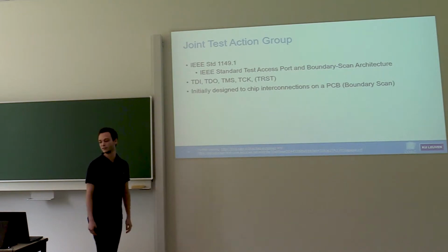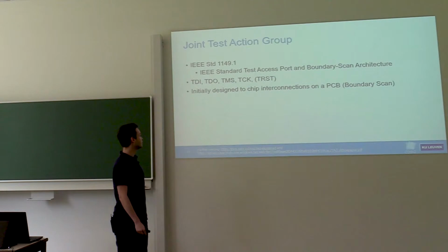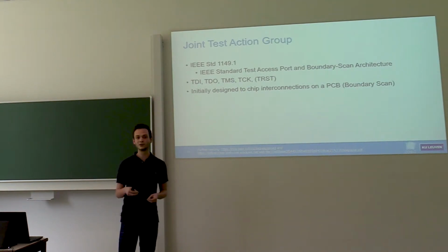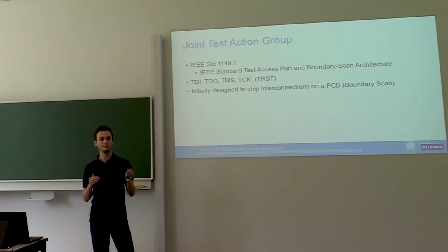JTAG stands for Joint Test Action Group. It's an IEEE standard that was originally designed to check if chips are physically interconnected on a board. So you can set any pin high or low and then see if this propagates to another chip.